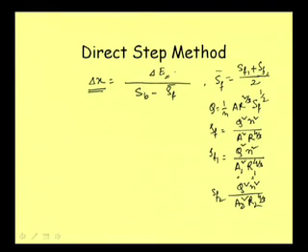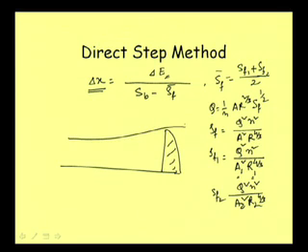Well, suppose we want to calculate a gradually varied flow, say this is the flow profile. We have first calculated yn and yc, and we know this control section depth, say y0. So we have got this value. From this known value, initially we know one value, and from it we can calculate this SF1.